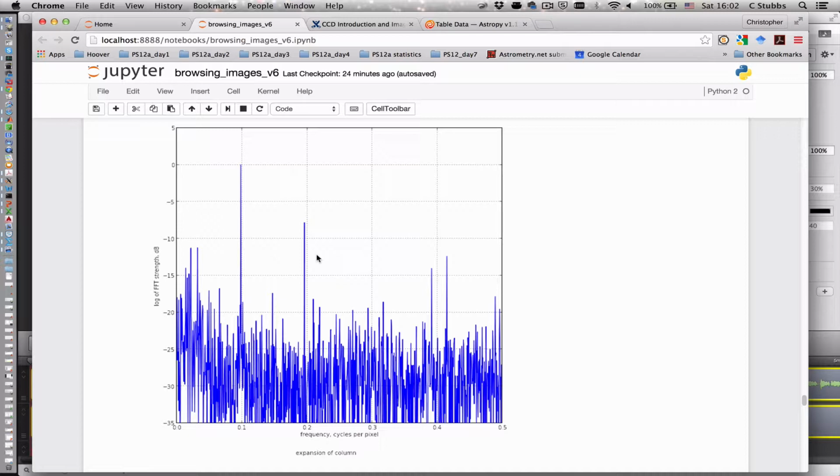So I don't think it's quite exactly a mask step repeat issue. I think it more likely comes about from laser annealing on the backside of the device. And we'll talk about that as we move forward here. But clearly there's statistically significant spatial structure in the array.